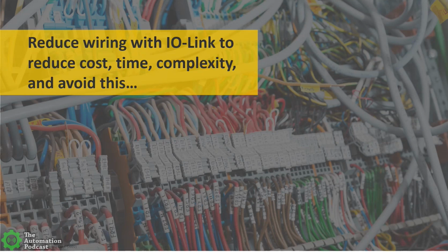And I've seen some great presentations by OEMs who have switched from hardwiring everything, getting the sensors with pigtails and hardwiring everything, to going to the slightly more expensive cord sets, right? And how much time they have saved, especially in troubleshooting. I've driven 3 or 4 hours to troubleshoot an IO card where the elderly guy who was wiring their panels just was not screwing down the screw heads hard enough, and so the wires were just kind of hanging there, not connecting. So this is real, and now eliminating.